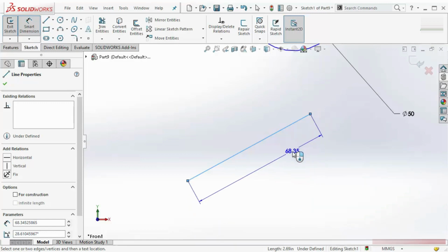If you want to restrict this change, let's say I am in this position and I want to put true dimension, you have to press the right mouse button one time, and next to the cursor you can see there is one lock option that is showing unlock now. So now if I move anywhere, you will see this is locked. If I want to unlock again, I have to press the right mouse button again and it will unlock again. At this position I want to lock it.